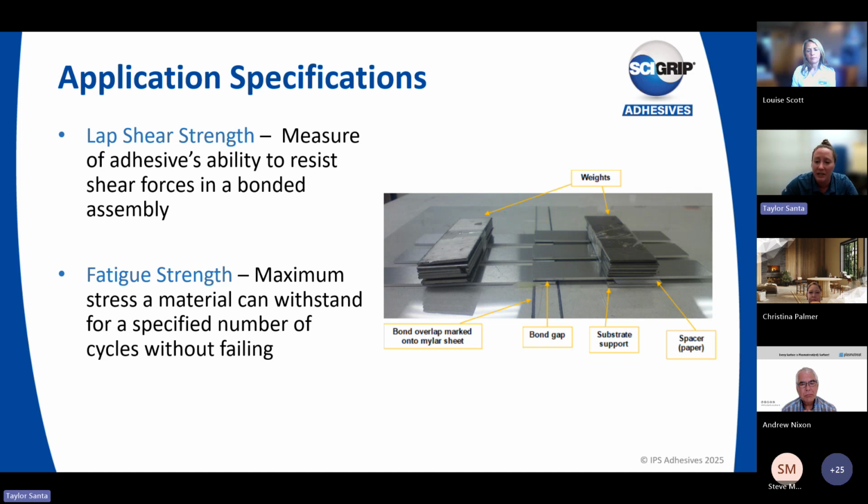The strength of the material here in that pulling mode is called lap shear strength. It is a measure of how much shear force can be exerted on lap joints before failure occurs. It's often tested during joining process qualifications or material validation to avoid a future failure. Lap shear strength is measured in PSI, pounds per square inch, for the most part.